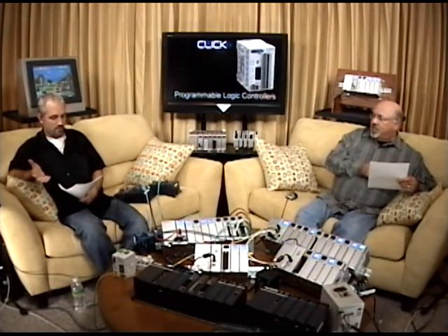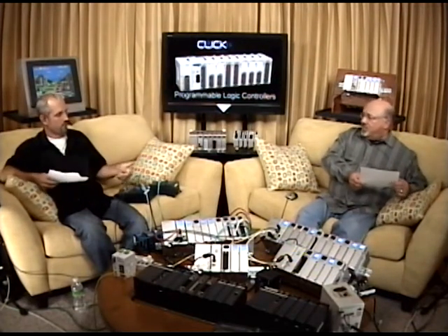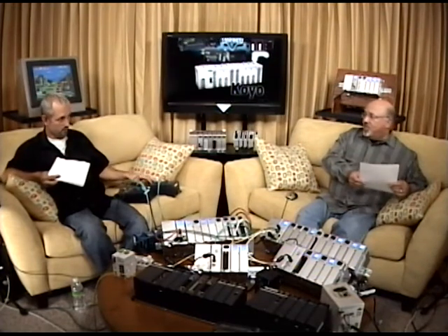Especially if you're doing master to slave, PLC to PLC communications, you might want to put that on its own little network and then have another ECOM and use that ECOM for, say, communicating to the PC. So if you isolate your network, especially with the Ethernet remote stuff, the ERM and the EBCs, you want to isolate your networks. We didn't mention that earlier.